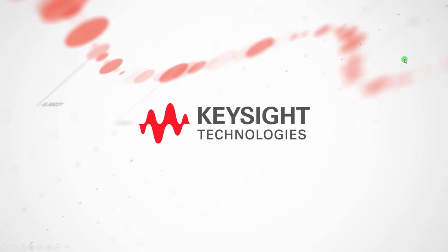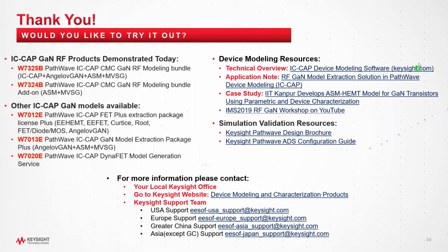So for anyone who doesn't have much time, I'm sorry for the delay. First, you have to have the DC, the CV and the S parameters, and for the trapping, you need to have different quiescent points. It really depends on your application. It's not really easy to tell you exactly which measurements you need, but DC, CV, S parameters at different biases, and different quiescent points of the device are definitely necessary. And if you want temperature dependence, of course you have to change the temperature. These two models also include the thermal parameters.